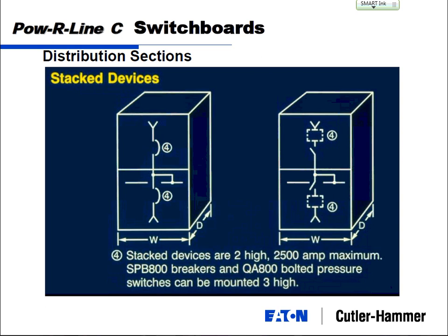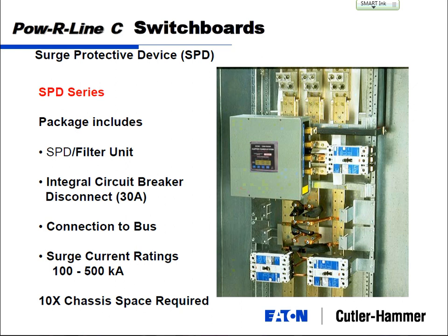On your switchboards, your feeder breakers, you can actually stack them. I mentioned 1,200 amps is a base you can put on a chassis feeder board, but you can put individually stacked feeder breakers just like a main breaker, which takes the limitation out of it. For SPD devices, the most important location is at your service entrance point. If that's a switchboard, we mount it like this, where we'll put a little circuit breaker in here to act as a disconnect right into the side of the unit.